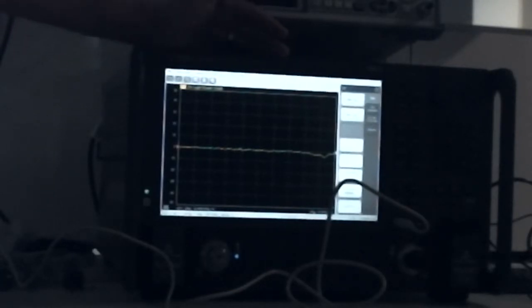Okay. So the reason you may be more used to using BNC is that BNC works up to about 1 gigahertz, right? The connector is rated to about there. The issue with using BNC to do really good measurements, and maybe this is what you have here. This is some of the items you purchased. So you have BNC, okay, and you have some SMA as well. Okay, you have some SMA, and it looks like you have some connector adapters. Okay, adapters. Okay, perfect.